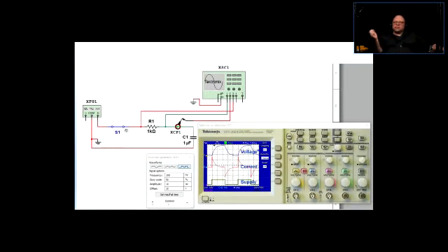Now, when we have established the current path, and sometimes you're going to have more than one current path, that's a really good way to analyze the circuit or start building it so you don't get yourself tied into a knot. And then after you have analyzed the current path, you're going to tackle the parallel devices such as voltmeters, oscilloscopes, or other things that are connected in parallel. Right? So what do we have in series? We have the current path established.